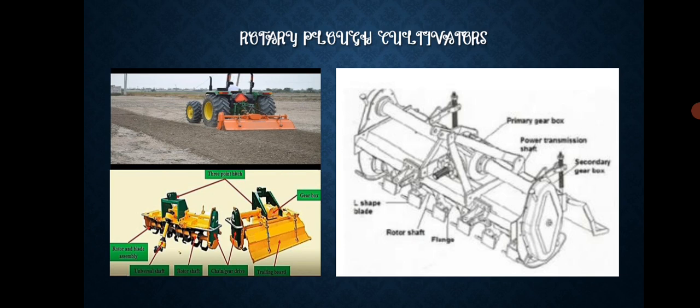Rotary tillage. The rotary tiller or rotary cultivator is widely considered the most important implement as it provides a fine degree of soil pulverization. It is generally mounted on the tractor and operated. The benefits of the rotor in the rotary tiller are effective pulverization of soil to ensure good plant growth, cutting and mixing of stubbles and roots with soil, and leveling of the field.